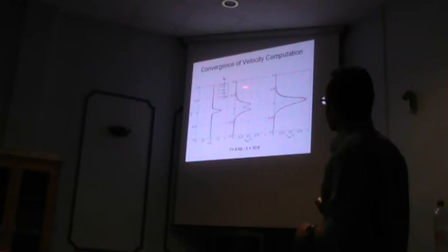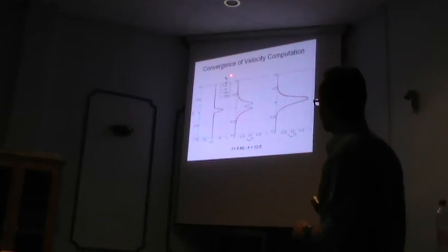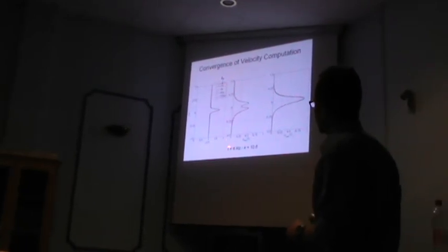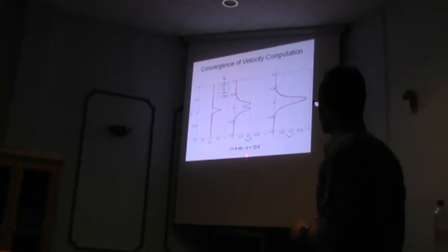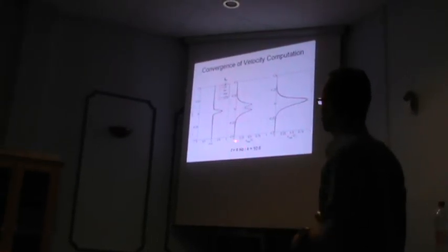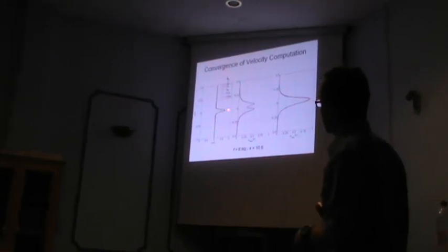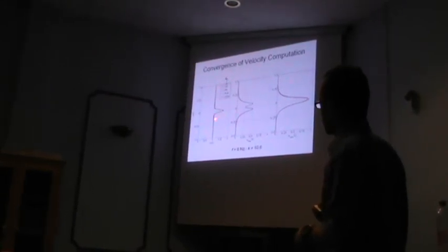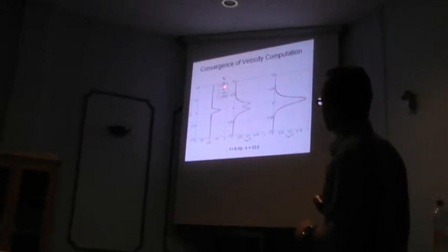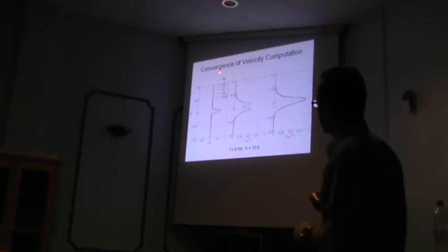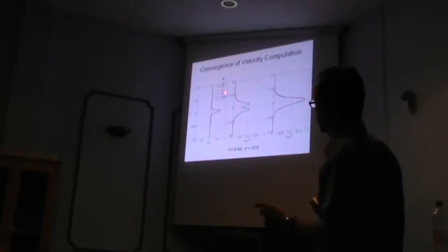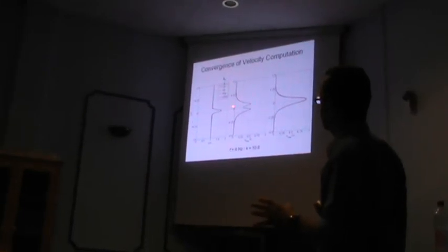Now, as far as Lx is concerned, what I show over here is a calculation just as an example for one of the cases, for an oscillation frequency of 6 Hertz. What you see over here is, as I showed with the visualization, you expect this kind of jet profile in the wake of the airfoil. We're repeating the calculation of our model where Lx equals 2 wavelengths, 4 wavelengths, 40, 320.